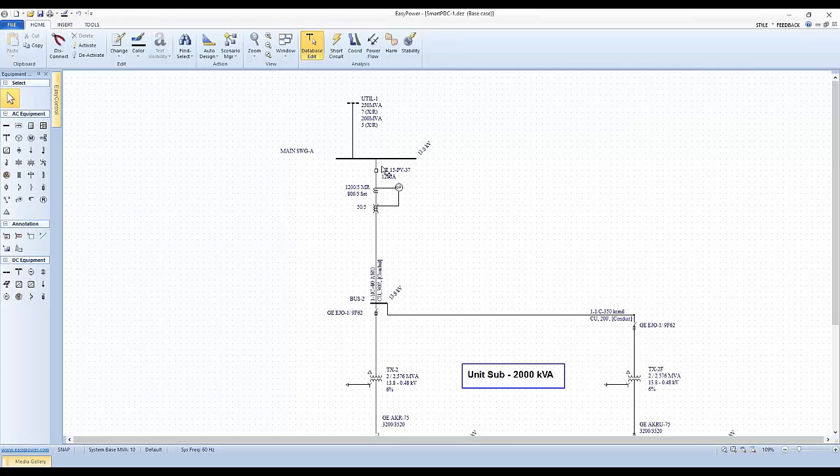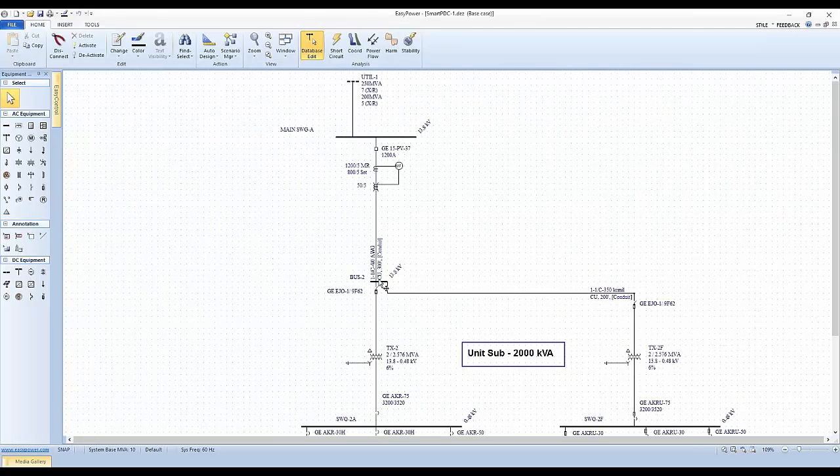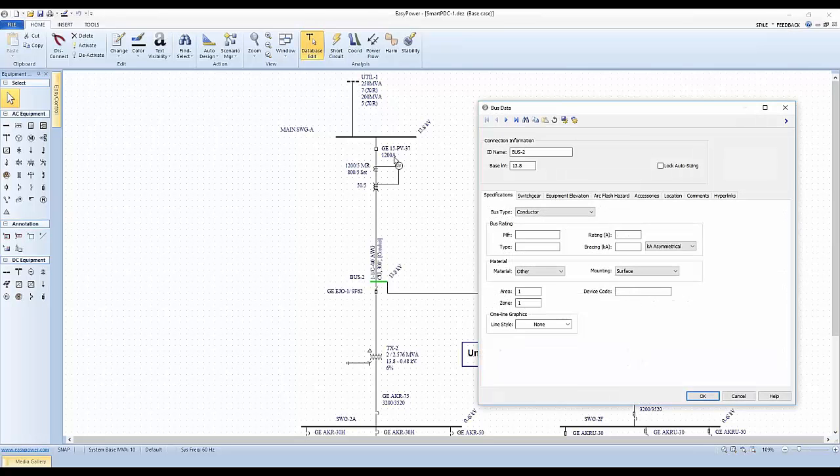If this were a differential relay or an arc flash relay that had a sensor in this bus or anything downstream, then the arc flash time for this bus would be based upon the delay that this breaker conveyed. And so again, it would be a time setting for the local bus, not for the breaker itself.